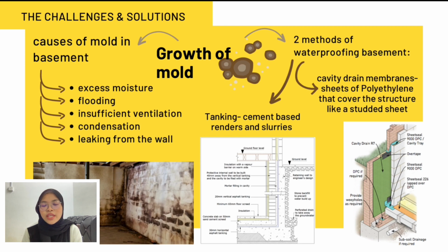The first waterproofing is tanking, where the objective is to offer a continuous waterproof membrane that is applied to both the base slab and the walls with total continuity between the two applications. Tanking can be used externally or internally depending on the circumstances at the location. Tanking membranes are frequently made of mastic asphalt, bituminous compounds, and epoxy resin compounds.